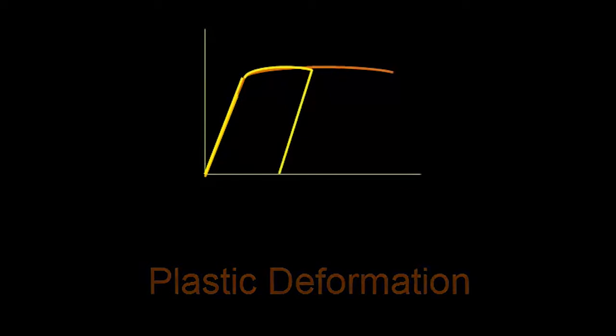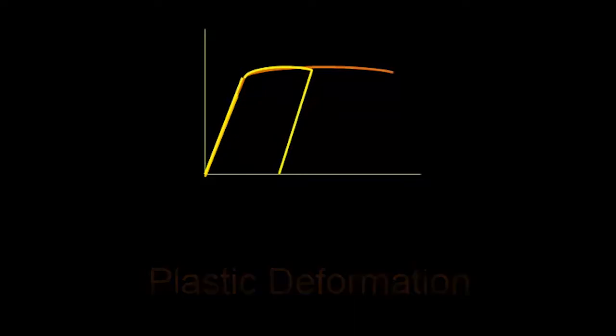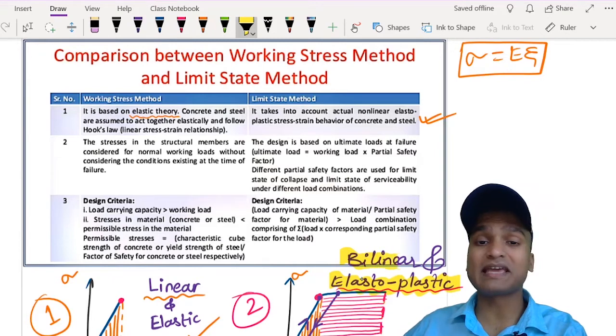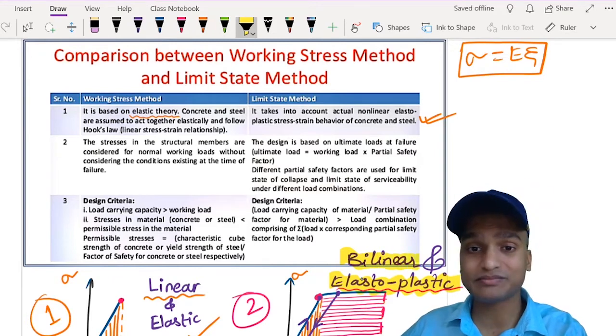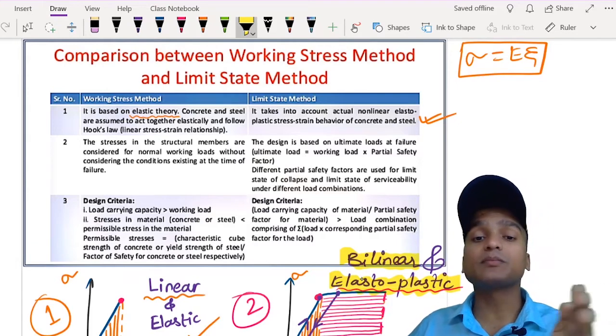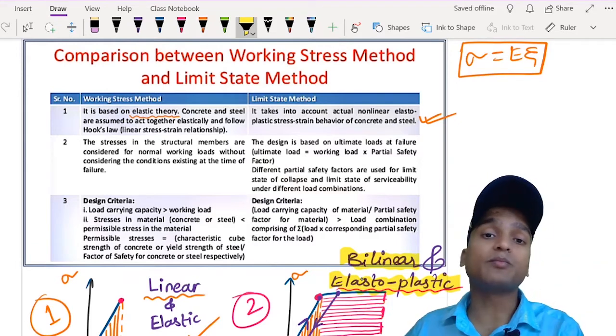This deformation is residual strain. Such a material is called an elastoplastic material. We can clearly see the curve is not just linear, but has become bilinear. And the point that differentiates the elastic region from the plastic region is the yield point.